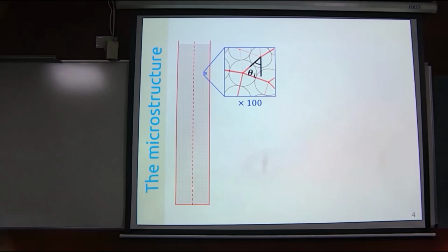We generate a packing from the DEM simulations. We divide it into a small grid, and we look at the contact angle at each grid point. This is a grid of 2 particle diameters by 2 particle diameters, and there are some hundreds of such realizations. So we have enough contacts in each grid to make some statistical averaging. Each contact has two values: one is its orientation, which I measure from the vertical, and the other is the contact force.